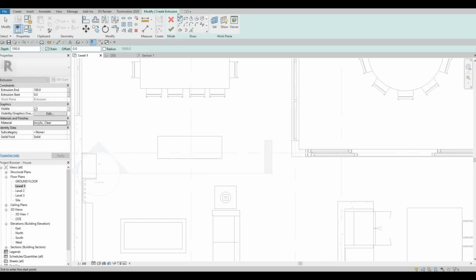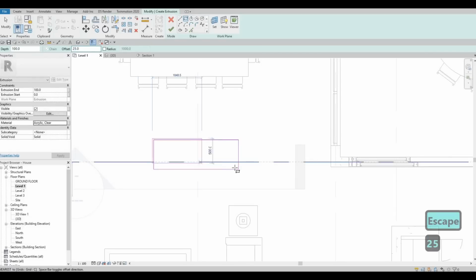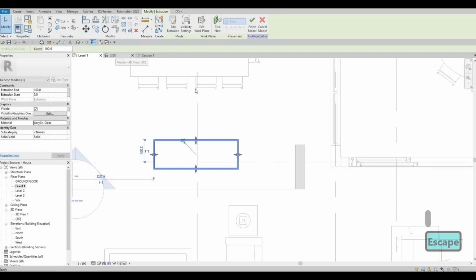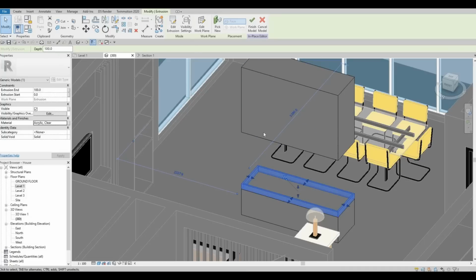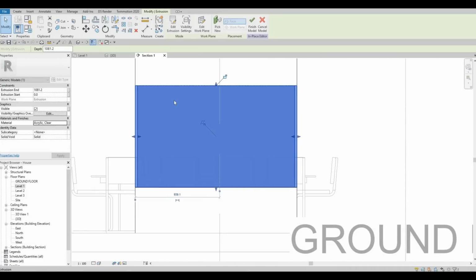We're gonna choose this plane again, and then here let's add in the glass, and then an offset, the thickness of the glass, let's do 10, so maybe 25, and then flip it going inside.